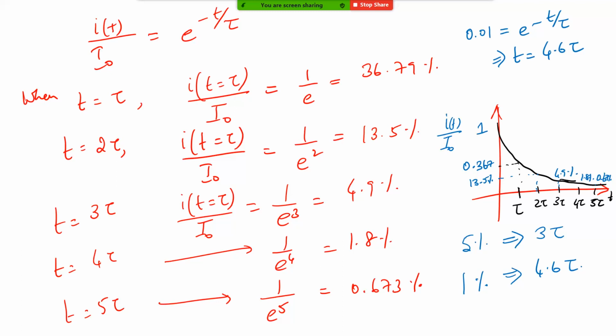So this is the behavior of an exponential system. Although mathematically the signal will asymptotically reach the final value, asymptotically means that it will never reach the final value, but only get closer and closer. It's only at t equal to infinity that we say mathematically it reaches the actual final value. But in any practical system, the notion of waiting for an infinite amount of time is absolutely pointless.